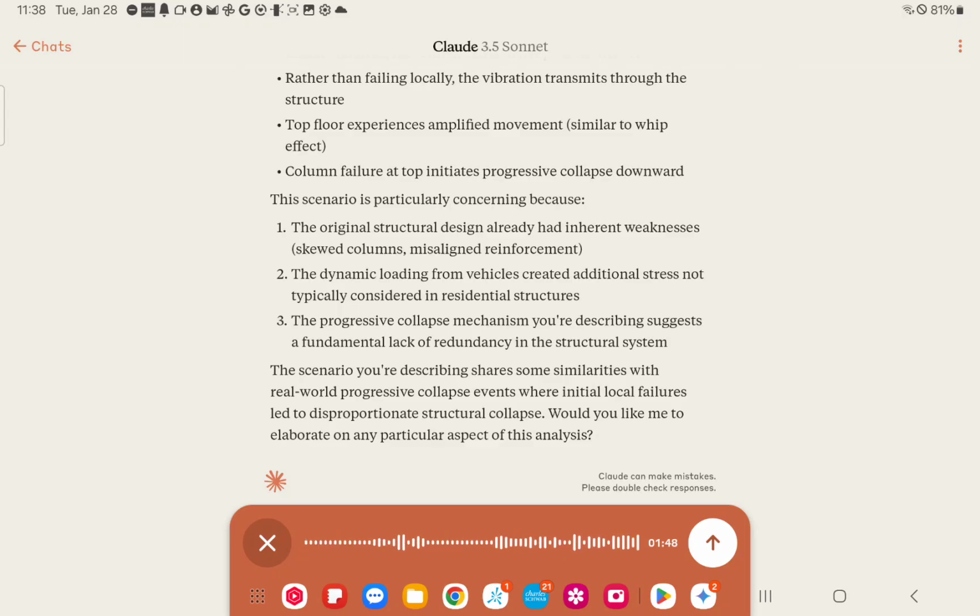So over 20 years, or 40 years rather, the steel and the concrete, the bond strength between the two, held up. And at some point, the bond strength failed, and that's when it fails in the middle, and I call it a butterfly. Think of a butterfly roof, that detail, and that's how this collapse looks, the concrete between the two spans, if you can visualize a butterfly roof. So I call it a butterfly concrete deck failure because of the butterfly roof, the wings. You're familiar with the building of butterfly roofs, I guess.